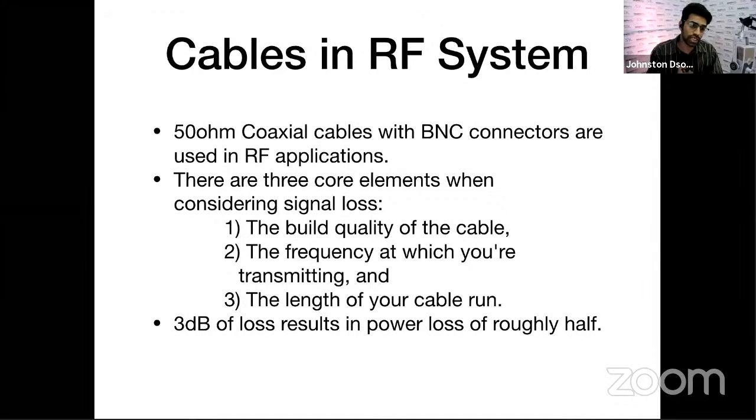So you need properly shielded coaxial cables with the right impedance on it. For that matter, even the impedance of the connector matters, because they're two different devices, right? You can't use just any random BNC connector. There are BNC connectors with a particular impedance value given to them.